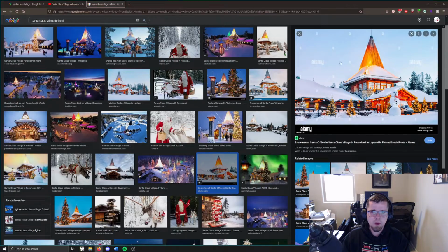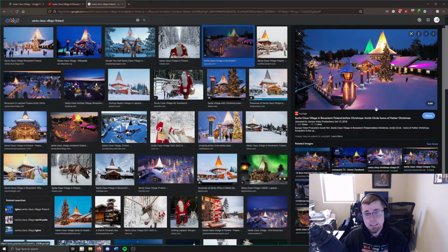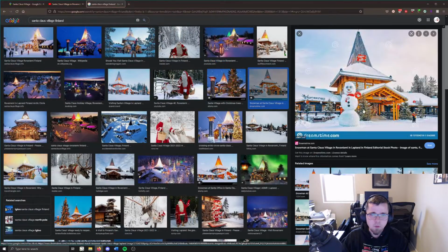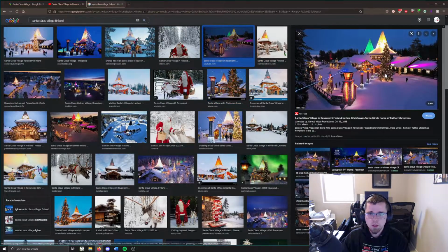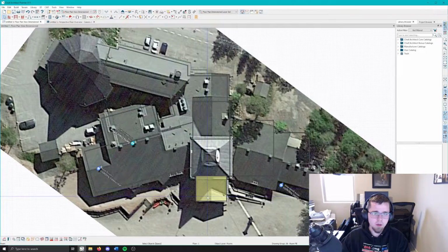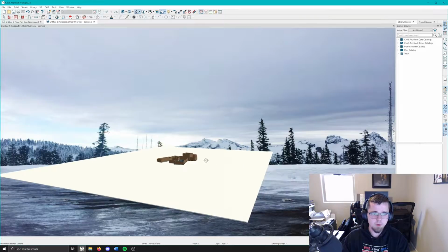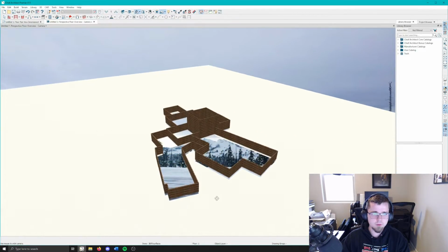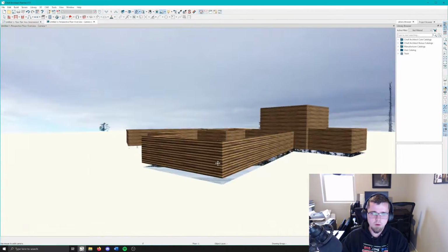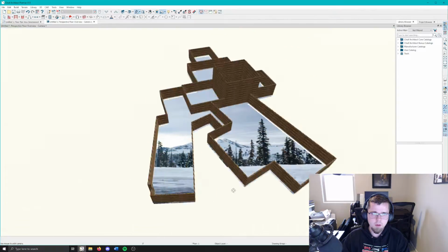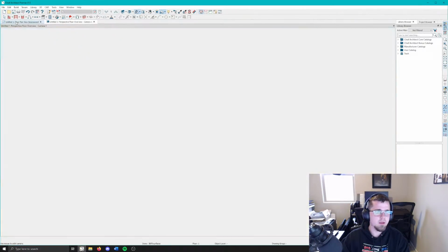Let's look back at our little reference pictures. All right, so looks like about the same ceiling height for everything except for the front, which looks a little bit taller than the rest. I could be wrong, but let's just go with the front being 12 and the sides being 10 foot. So we're gonna take this, give it a 12 foot. I already have these others defaulted to a 10 foot, so I'll leave them for now. Okay, let me turn off my little intersection here. Okay, so, yeah, you know what? Sure, it's close enough, right?